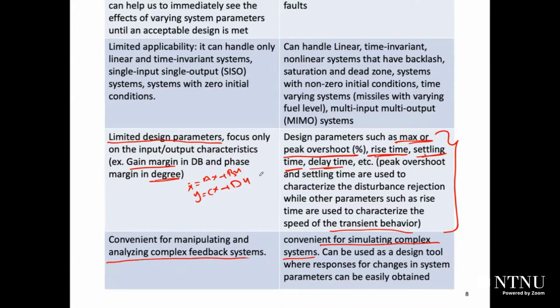In fact, in time domain, you just need to define a for loop and you need to calculate x dot. So I will just calculate x dot equals Ax plus Bu. And if you want to get x, in fact, x will be x plus x dot, correct? That is it. So it's a kind of integration. In the system here, we try to integrate. And once you calculate x, you need to calculate y. So substitute this value into this equation to calculate y. So if you want to simulate your system, I will give you an example in Python at the end of this chapter, where you can try to simulate your systems in the time domain.